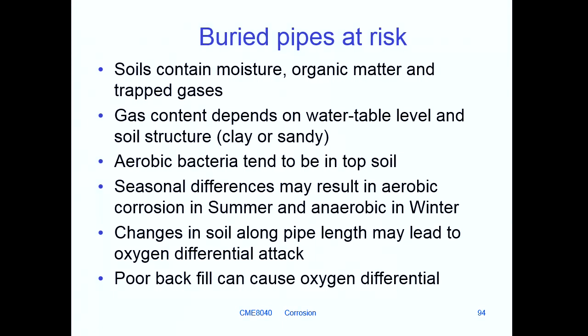So you've got a situation where your pipe may or may not be experiencing times in the summer, perhaps when the water table's below its level, and in the winter when perhaps the water table's above its level. So that's one issue which you get, seasonal differences, taking you from aerobic conditions where the water table's below the pipe to anaerobic conditions where the water level's above the pipe. That's not to say there isn't a bit of moisture in the soil dotted about, which is enough to help the bacteria, but actually having a saturated soil level is changing.